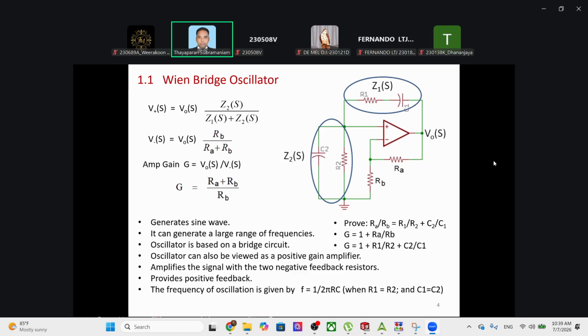Okay, less than 1%. So if you want to have 0.5 milliamp, then what's the supply voltage? The op-amp supply voltage, minimum supply voltage, maximum supply voltage, you have to choose one. That's why op-amp selection also matters here. If you choose arbitrarily, then you are compromising your power consumption. So when you choose an op-amp, you have to choose the right op-amp.